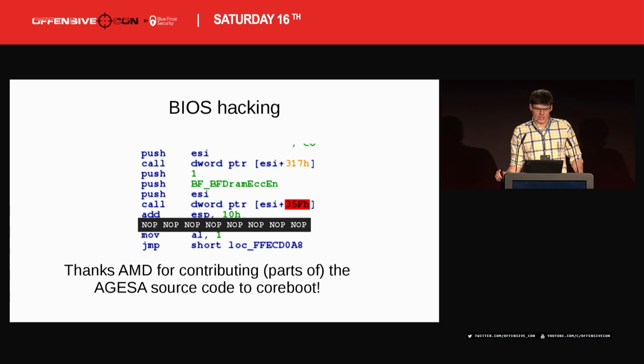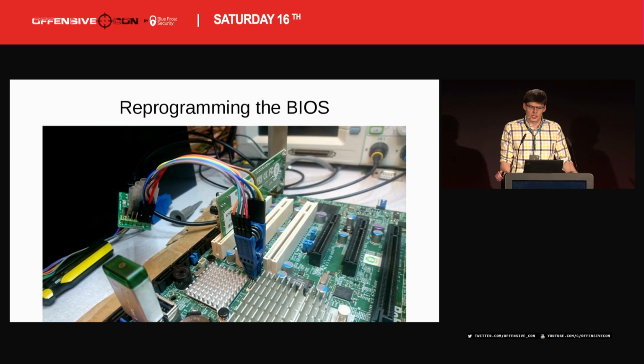This goes in the direction of Alex's introduction, the keynote speaker from yesterday. You have to look around when you're doing reverse engineering, and we observed that some similar code was contributed to coreboot by AMD, and this code included the memory initialization part as well. That was kind of cool. There was some checksumming bypass happening at some point, but I won't go into details. I had to reprogram the BIOS chip several times. Not really that complicated, but it took some time.